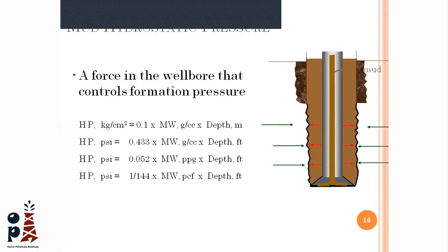When we are pumping the mud, we use a mud pump with a certain pumping pressure. This pumping pressure is lost during the whole journey of the mud from surface back to surface. Guys, I'm talking here about the pump pressure. We lose this pressure through all well components, starting from the surface line, then the inside of the drill string with different sizes, then the bit itself.